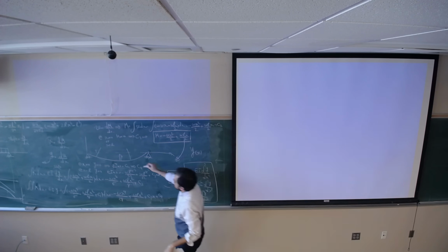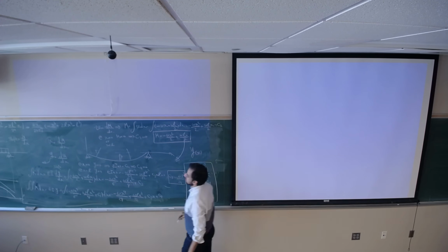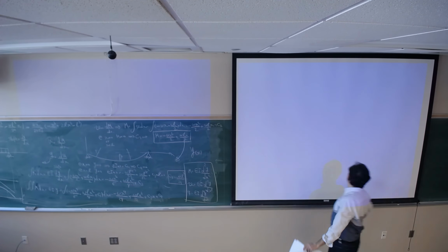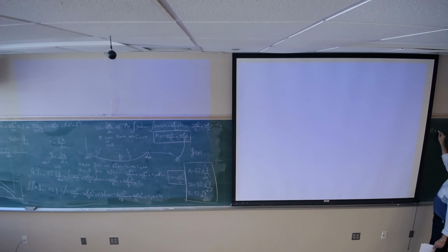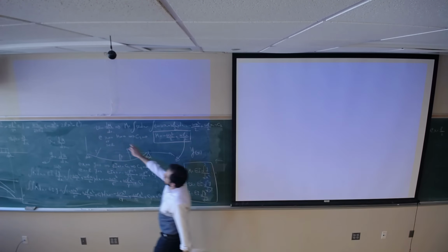And if I ask you at which point of the beam we are going to have the maximum deflection, for this type of loading it's obvious that the maximum is going to occur at the midpoint. So at x equals L over 2, just plug in x equals L over 2.